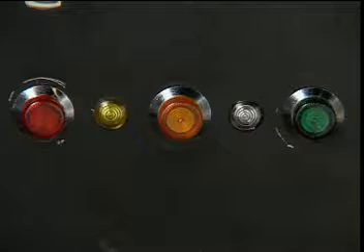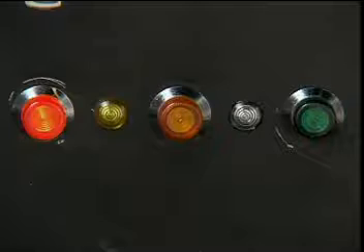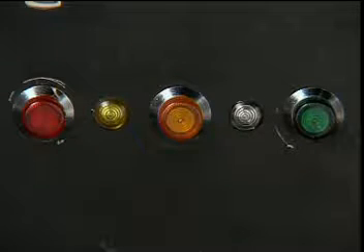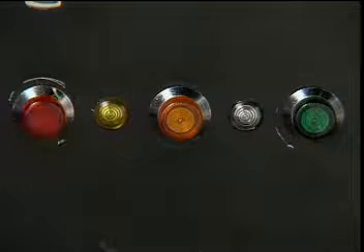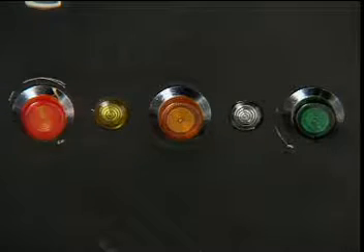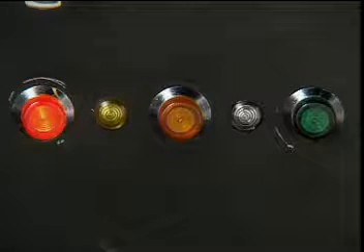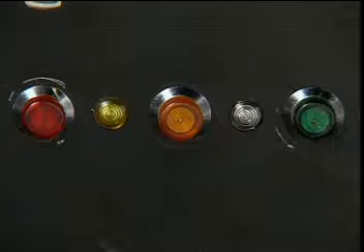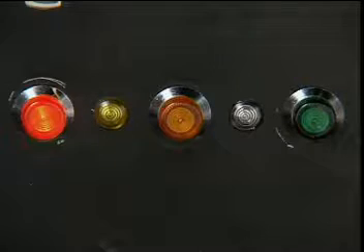Beginning with the first active quantum fault, the red lamp will flash out the first digit of the 3-digit fault code. After a 1-second delay, the red lamp flashes out the second digit. Then, after another 1-second delay, the red lamp flashes out the last digit. After the last digit, there is a 2-second delay, and then the next active quantum fault is flashed out.